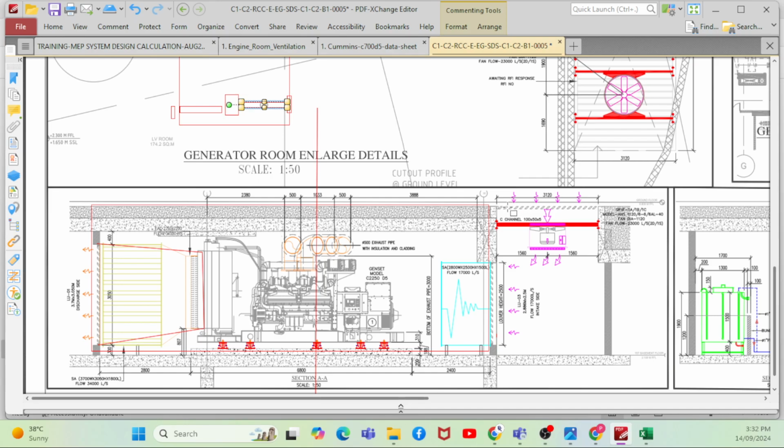So this particular louver, say for example this is my louver, of course with an enclosure, an aesthetic enclosure with the louvers. When people walk here, they can hear the fan noise. So in that case, what we did is we shifted the fan from external to internal. We kept the fan internal, within the generator room itself.